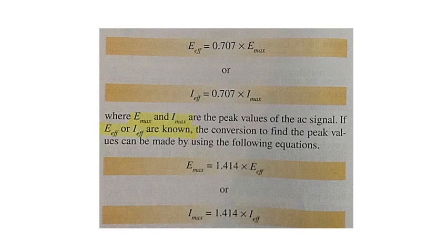The effective value is also named the RMS value, or root mean square value. It gets its name because the value represents the square root of the average of all currents squared between 0 and maximum of the wave. The currents are squared so the power produced can be compared to direct current. Watt's law states that power equals current squared times resistance.